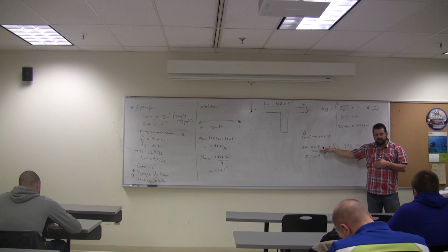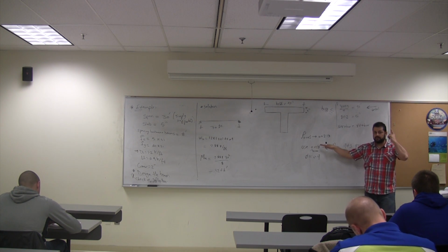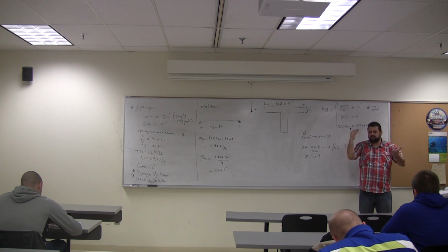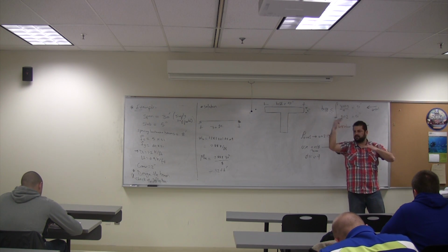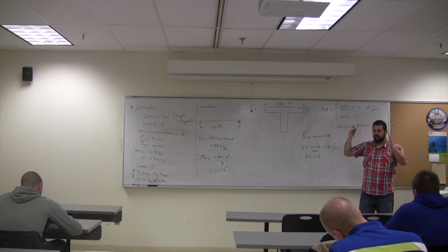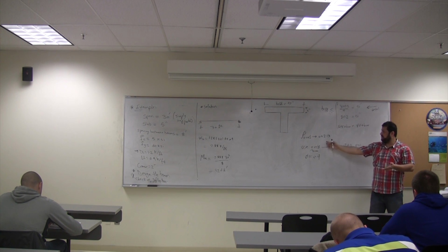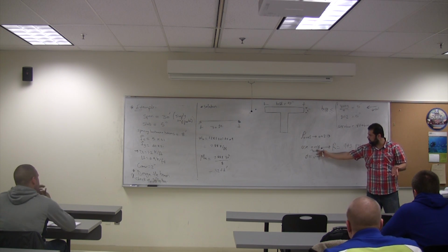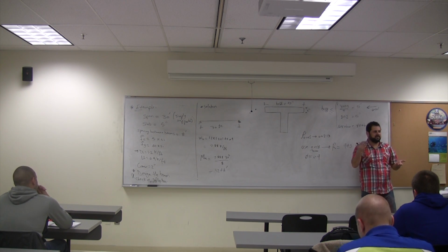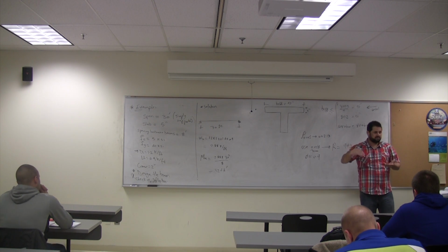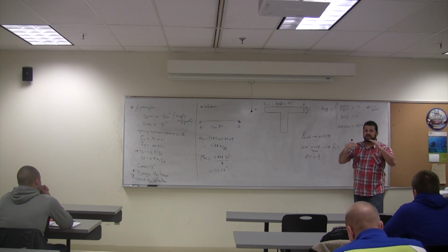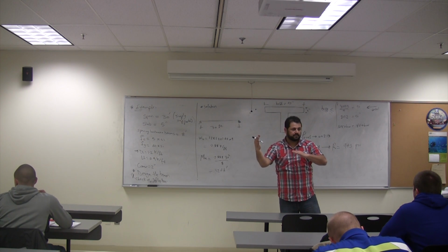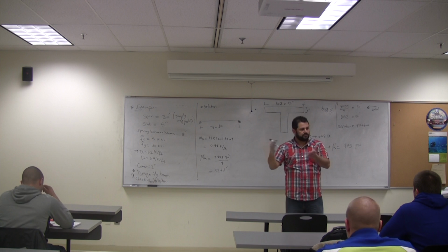Why I went with a high value here? Look, you guys, you understand what I'm saying? I'm trying to minimize D. For no reason, just for me. I don't want to go with a large D, so the architect later on can tell me, hey, this is D. So you can come with even the full rho like 0.02. That's absolutely fine. You can go with 0.015, say no limitation about this, so I don't care. I'm going to reduce the steel in my design. Not reducing the steel, it means I'm not reducing the steel. If you reduce the steel, you increase the concrete. If you increase the steel, you decrease the concrete. You know this, it's a balance.